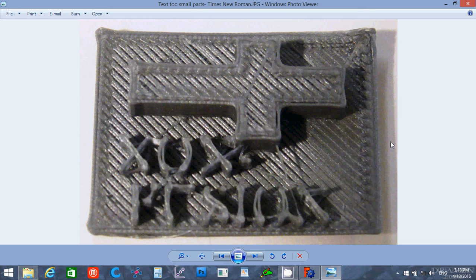If your 3D printer's nozzle is 0.4 millimeters, then your minimum wall thickness is that size. If you go below that or get too close to that minimum, the slicer program itself will just ignore anything that's smaller than that. And so parts that disappear are usually because of that issue, that you've gone too small, because you're not meeting the minimum wall thickness.